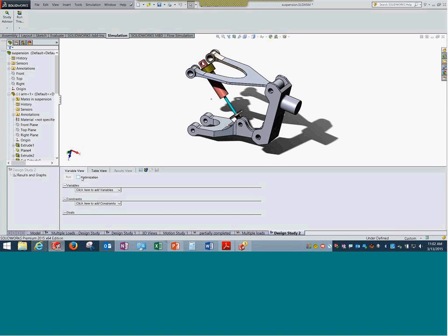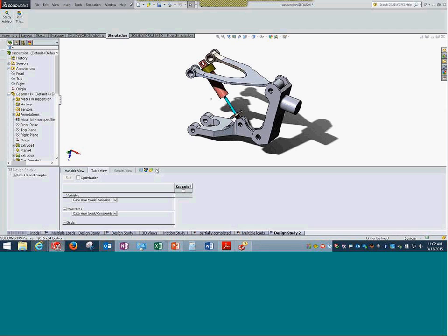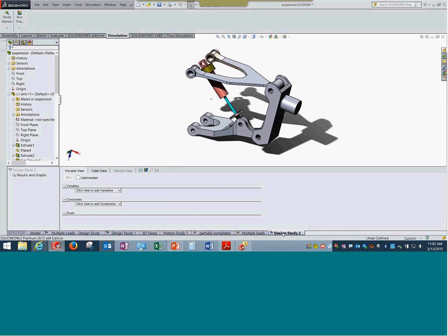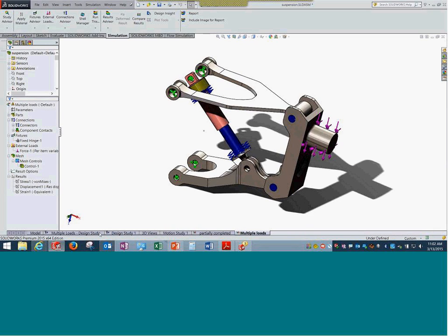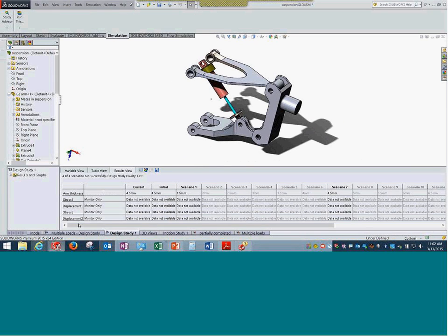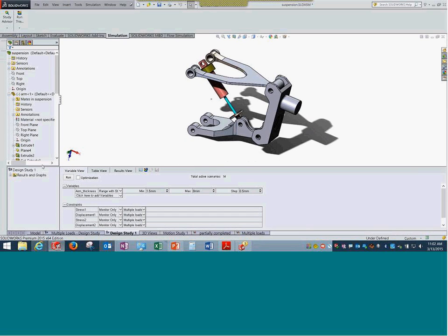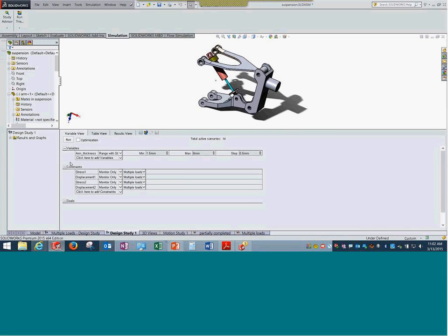It is more of what we do is we change certain variables in the setup, and thereon we see the results as a variation of those variables. Okay, go to one of the designs that has been created. Let me go to the variable tab. So if you observe here, the option this front end is giving is we can actually change. In this case, we are changing the thickness in the option range with step.